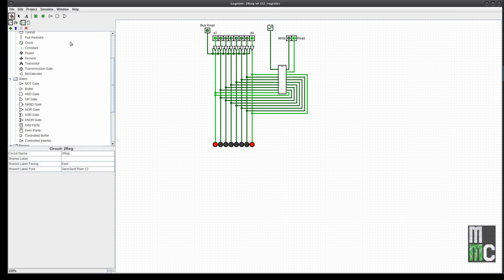Okay, now that I have that hooked up, I can choose where I want to output. Am I outputting from the register over here by clicking this read, or am I outputting from the bus here? So obviously I can put two different values. Let me put this value, the inner 4, it's 2 through 5 on. And you see no values here because we have not output anything. I select this that says read. That then says we move the value that is on our switches to the bus. Now I can do whichever one I want. You see there I have stored first and last on, 0 and 7. And here I have stored the other.